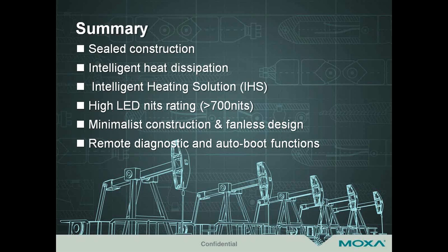You'll probably have to have ABS or DNV certifications that have to be marine grade. The entire unit will have to be IP66 minimally, Class 1 Div 2, and everything attached to it will have to fall under that categorization as well. So wires, busing or whatever, however it's attached to the operation, need to be insulated properly.